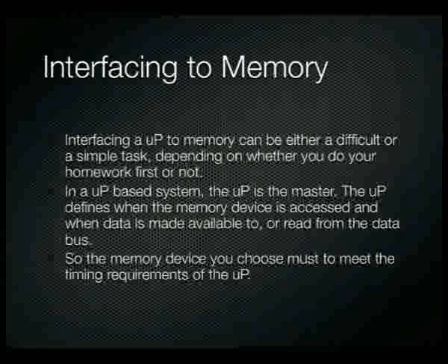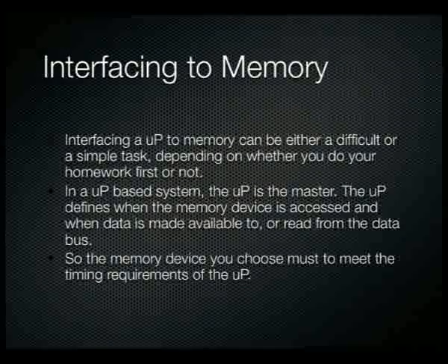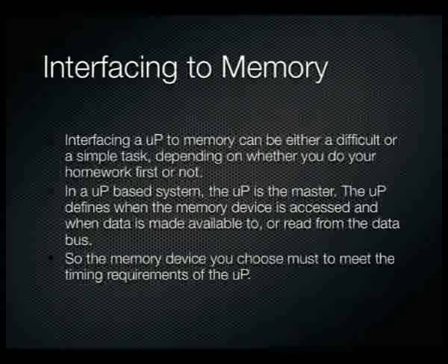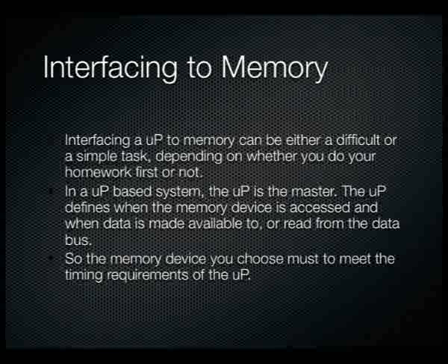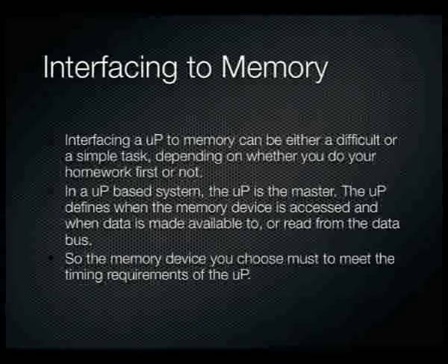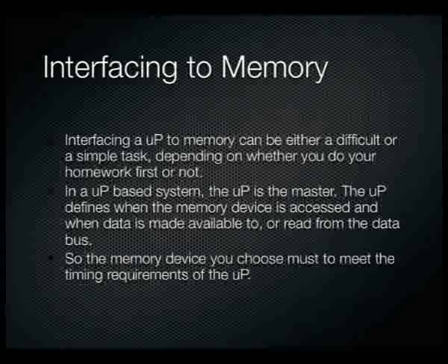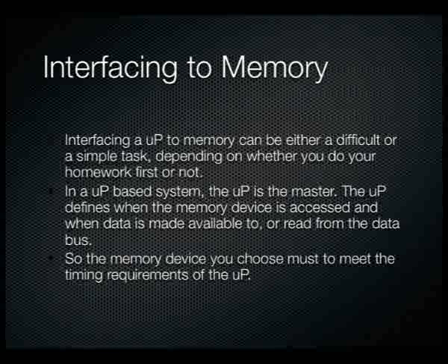So when it comes to interfacing to memory, interfacing a microprocessor to memory can either be difficult or easy, depending on whether you've done your homework first or not. Before jumping into designing an embedded circuit, you need to think about what the requirements of your microprocessor are, what its timing requirements are, and what components you can use that actually meet those timing requirements.